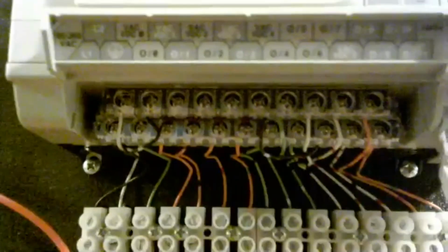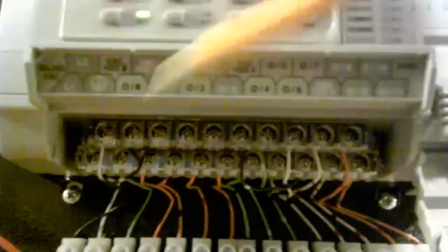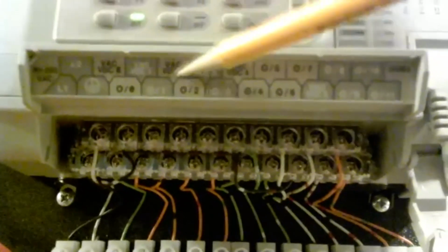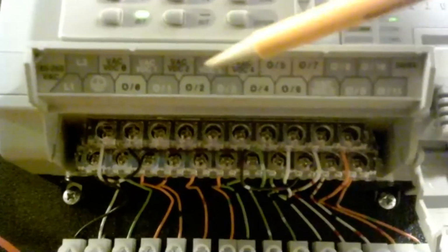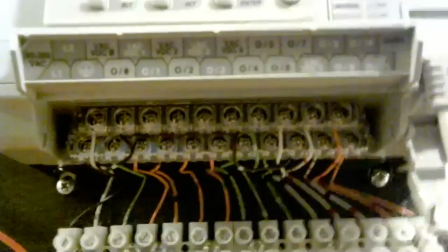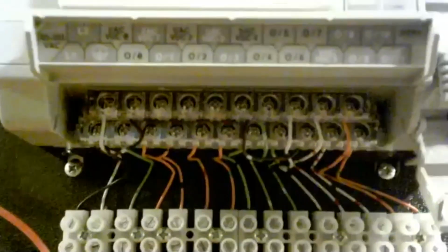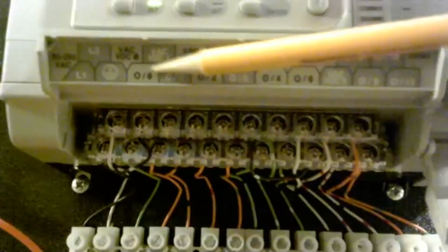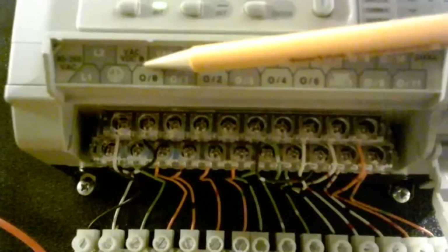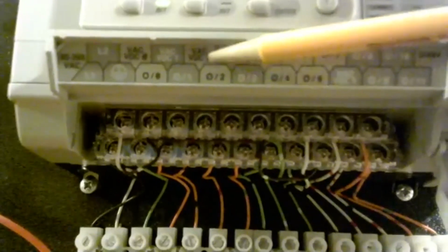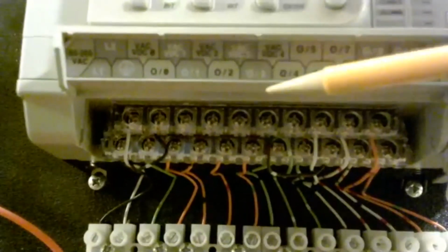the requirements of each PLC, and it's going to be different. For all the outputs, anywhere where it says VAC or VDC, you physically got to put a hot leg there of whatever voltage level you want to appear on the output, whether it be a DC signal or an AC signal. VAC 0 is just for that. VAC 1 is just for this. VAC 2 is for here. VAC 3 is for here.